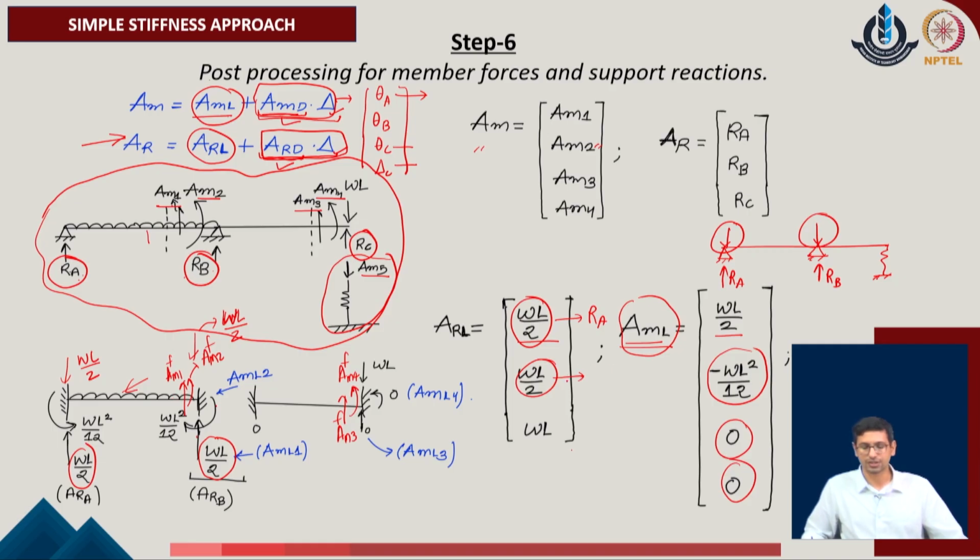As I am writing these systems as reactions, so for the value of the load which we are identifying, either I have to reverse its value or I have to just consider the value which is appearing with respect to the fixed ended reaction in this given system. So, this is the second component with respect to R of B, and finally, with respect to R of 3, which is the reaction at the support C, I realize that there is a load of WL directly active here. So, corresponding to that, I will have a direct reaction at that point, and that is R of C component of the given problem. So, with these three components being evaluated, one can now evaluate the effective net resultant value of the system reactions as well.